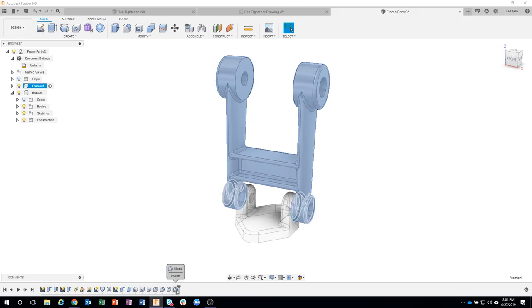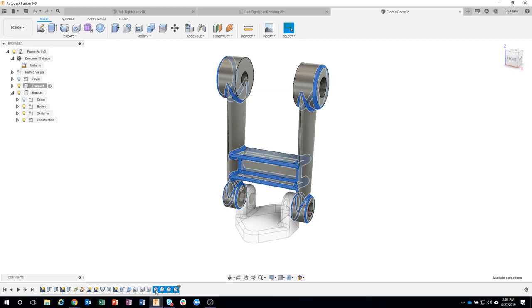And I've seen this question a couple times, so let me go ahead and cover this. I'm going to select all 4 of those fillet features, right mouse click, and you can see we can create a group. And you'll notice that it's now a single icon, and if I hover over it, it shows all of the features that are inside of that group. And I could expand that open to see them, or I could minimize them. But my favorite thing is you can rename it. So I'm going to right click and say rename, and I could call this small fillets or something like that.